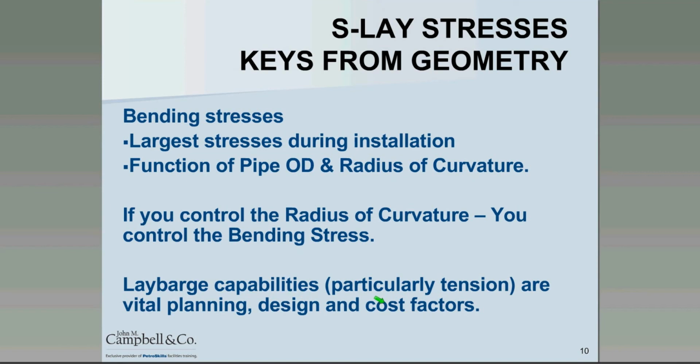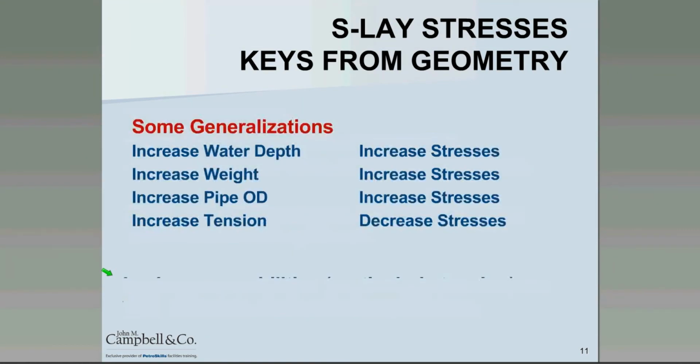We can make some generalizations about the geometry based on the very quick evaluation that we've done here this morning. If I increase water depth, I will increase stresses. I think that makes sense to anyone. I'm going to have a longer span from the surface to get to the touchdown point on the seabed. I'll have longer suspended spans from the truss or stinger to get to the seabed. I'll usually have higher stresses as well.